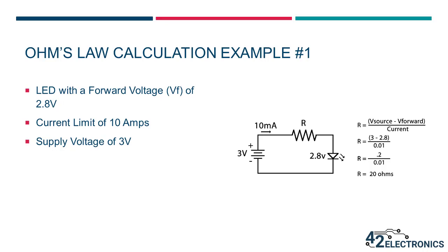Later in this course, you will power the breadboard using the Raspberry Pi. And since the Raspberry Pi is a small computer, it can only output a limited amount of current. So keeping the LED current to a minimum is actually a really good idea. Good habit to get into.